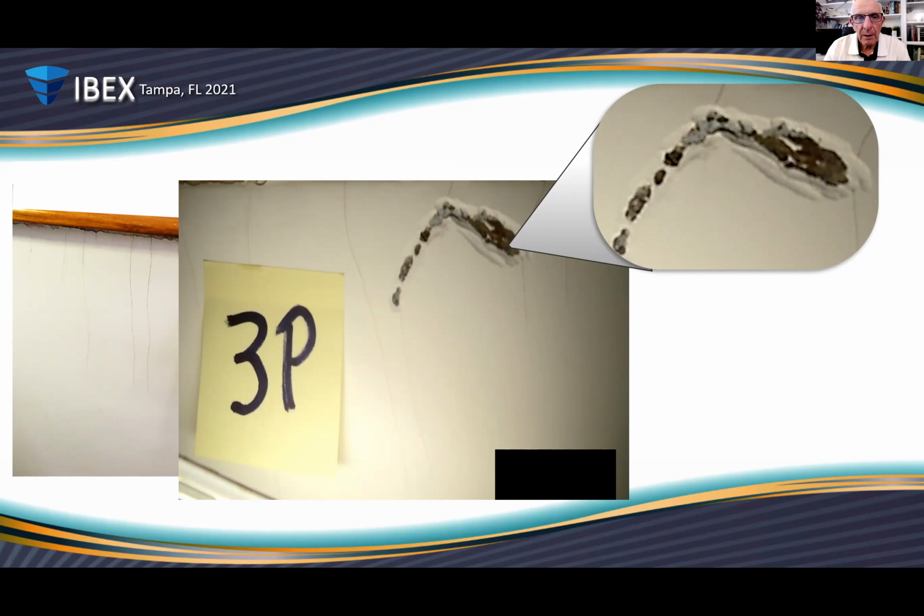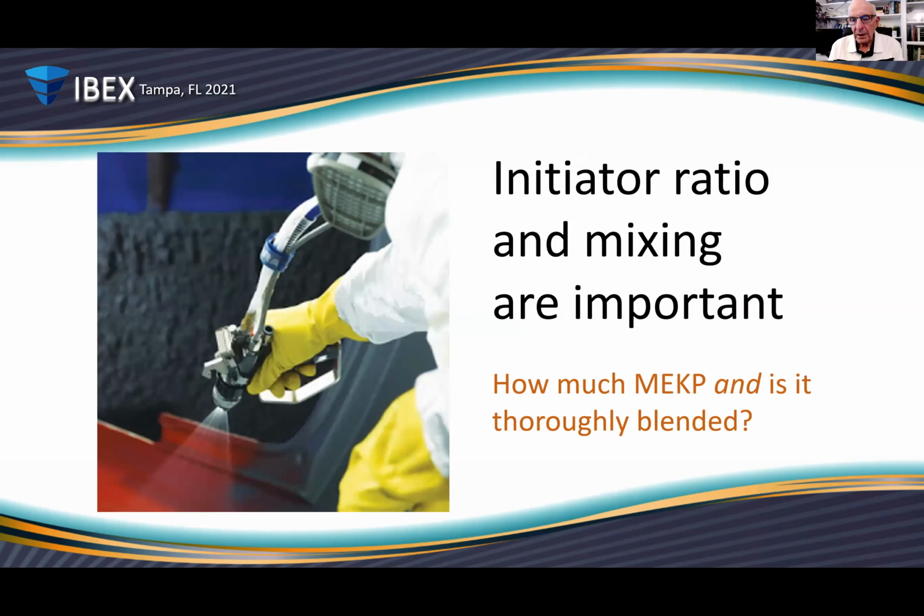If you look at the, I'm going to call it the rub rail area, the top edge of a flying bridge, a lot of times the gel coat is over thick and tends to crack in those specific areas. It's a place where you find cracks on a routine basis. So gel coat thickness is very critical to the performance of gel coat and preventing cracking.